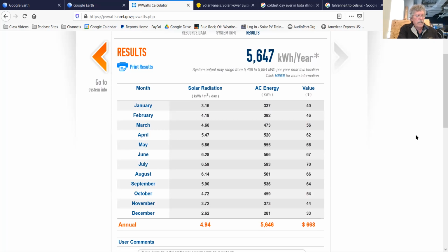So let's just say, if it's a string inverter, we're going to have plus or minus 5% for the various panels, because everything in this string is going to be plus or minus 5%. So that's going to take us up to 11%. All right, so let's say 11% derate or an 89%, because I'm going to do this one using a string inverter just so that we can do our string calculations, things of that nature.